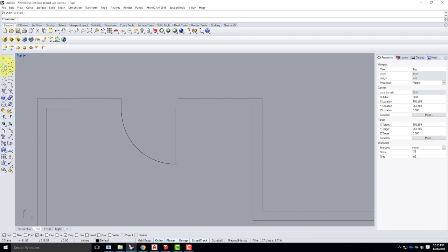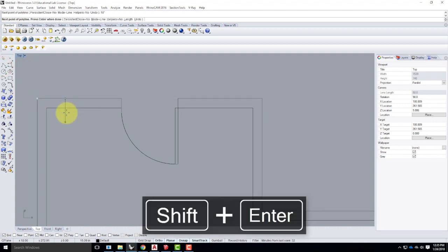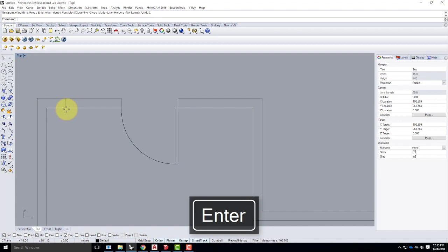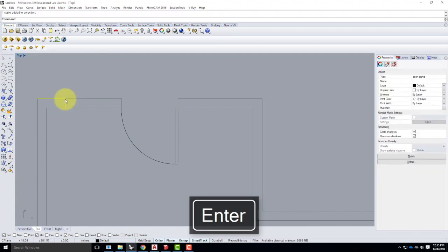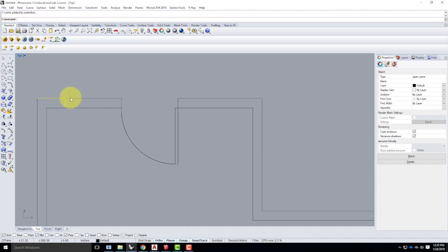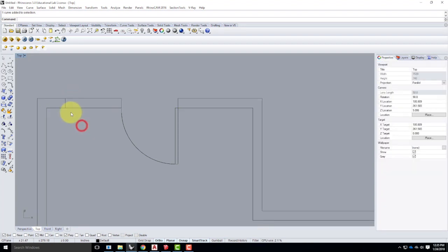And so what a lot of people do by default is they say, oh, okay, let me get a polyline. I'll start at this corner, and I'll go 18 inches. There it is, and I'll draw down, and there it is. Perfect. I've got my line. The problem with that is, yeah, you have your line here, but you also have a line there that overlaps with this line. So you have 2 lines on top of each other. That's not good when we do our extrusions. So we want to be clean.